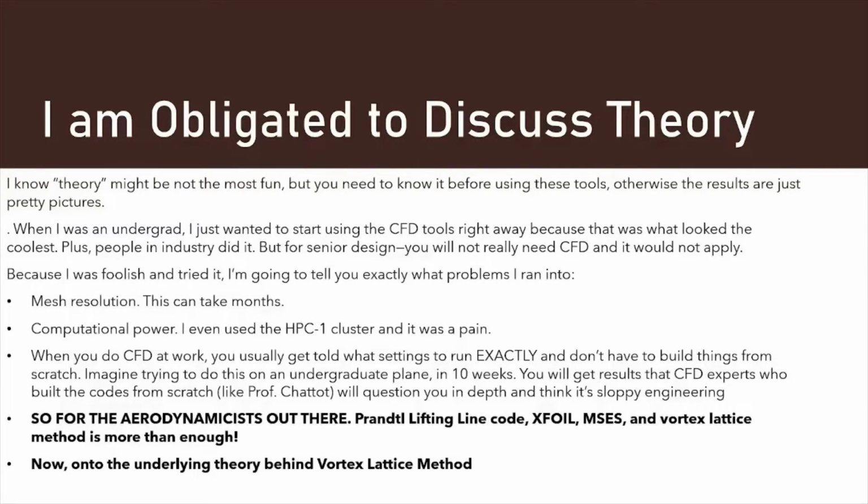So for the aerodynamicists out there, especially the ones that really want to do this, I promise you, just learn Prandtl lifting line code, XFOIL, MSES, and vortex lattice method. That is more than enough.